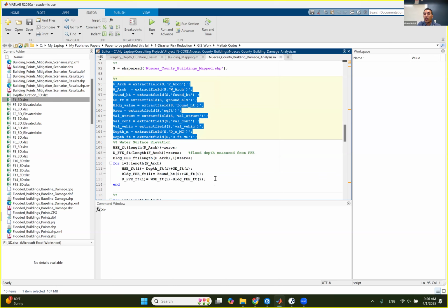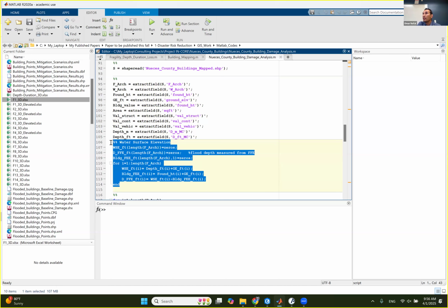All right, and you are calculating the same water elevations the same way, but try to name the water elevation that you extract from GIS with the same names here. Look at this field. Make sure that the name here matches the one in the shape file.